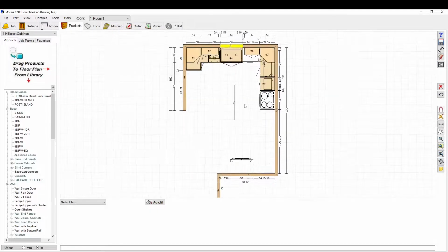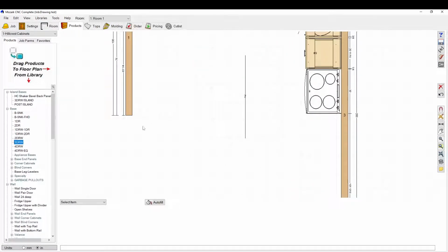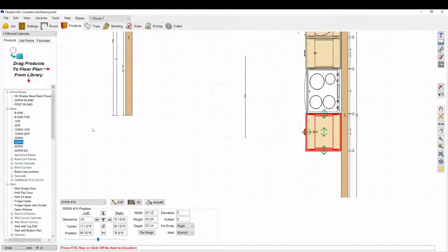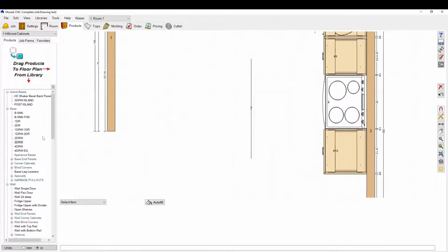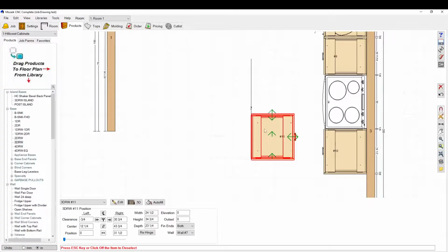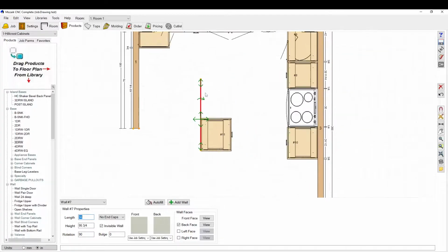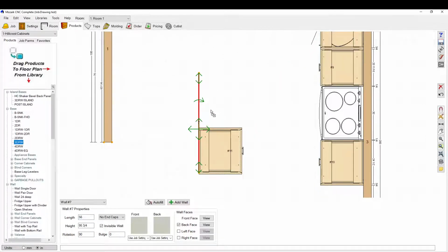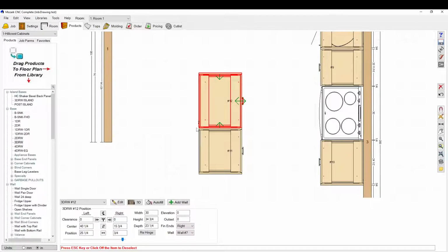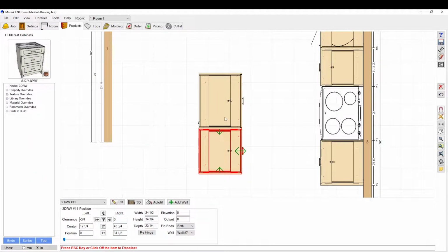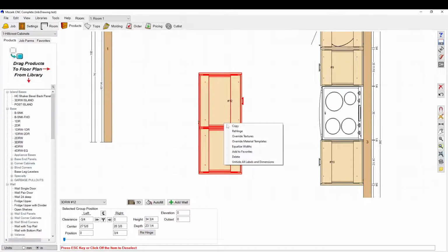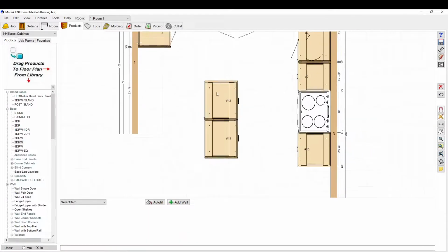So let's just drop a few cabinets on. We'll drop one on the right side of this. I will drag in a 3-drawer here. This island's way too big for this little room, but that's okay. We're just going to do a really little island. One handy feature is, I'm going to make sure I only have the finished ends I want. So I want a left side finished end. You can select 2 cabinets and then equalize the widths. That will make them the same width.